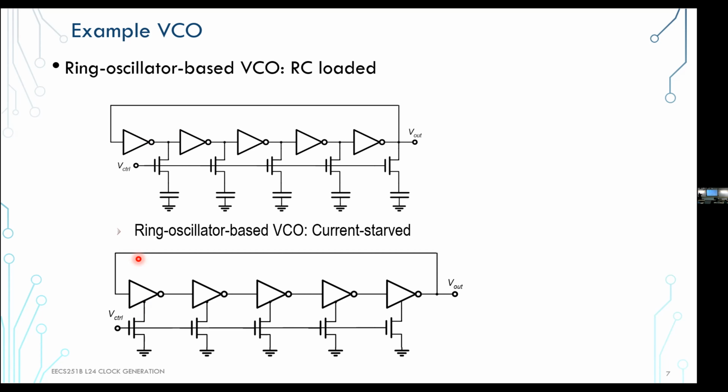But you have these two cases, right? So here in the very slow edge, small voltage change results in big timing error. Here, a small voltage change results in small timing error. So if you have a well-running ring oscillator, with very small delays, so sharp rise times, that one is less susceptible to supply noise, or even its own thermal noise.